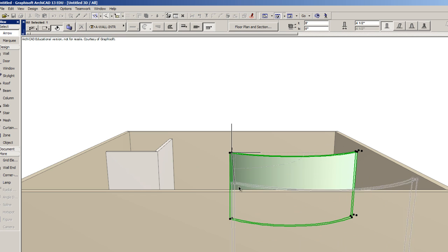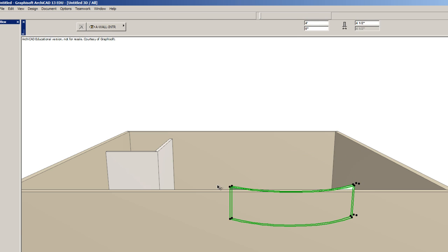And you'll see that right now the tool on the flyout that I have allows me to move the wall around. It's not what I want. I can make it go different elevations. I can rotate it, all sorts of things. I can even angle it if I want. All I want to do is change the height. So I'm going to stretch the height, and my tracker shows back up, and I'm going to not really stretch it, but shrink it. And I'm going to bring it down, and I want it to be 4 feet tall. So I'm just going to enter 4 and hit enter.